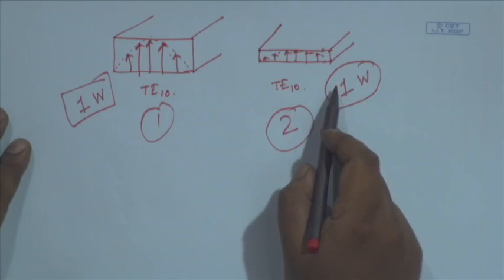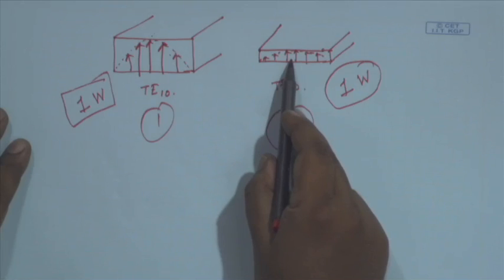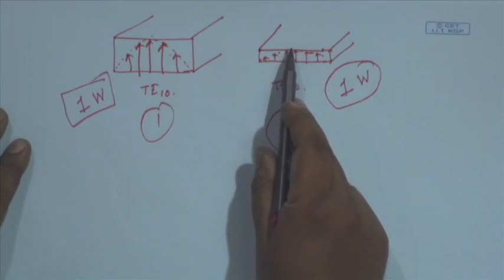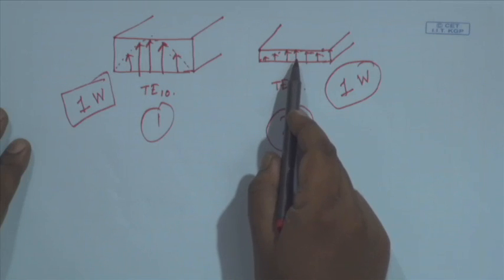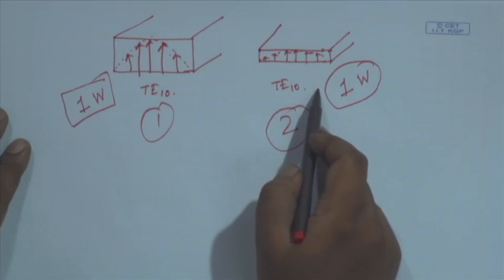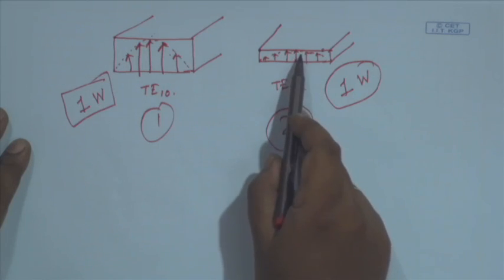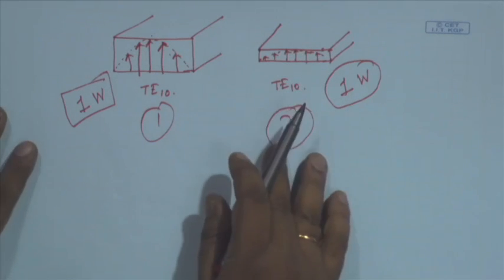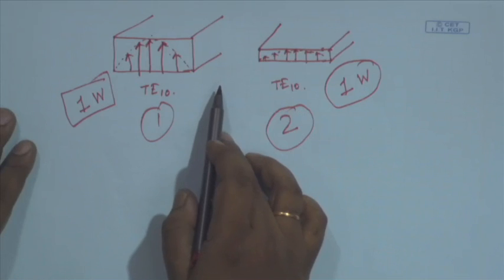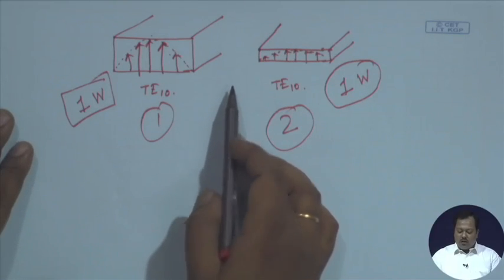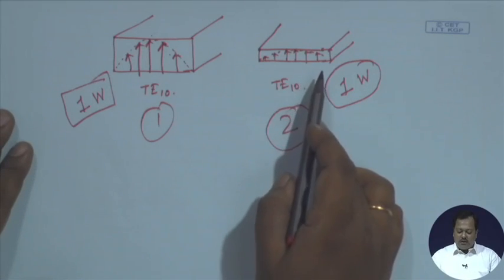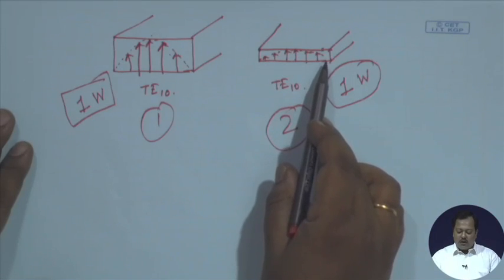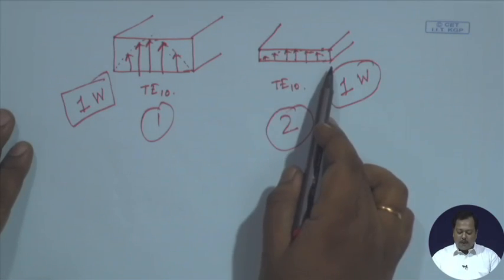Not only that, the electric field value as well as the loss are both increasing. So, power handling capability will decrease for case 2 and loss will increase for case 2. This is one conceptual explanation of why loss increases with reduced height, or with decreasing cross sectional area.